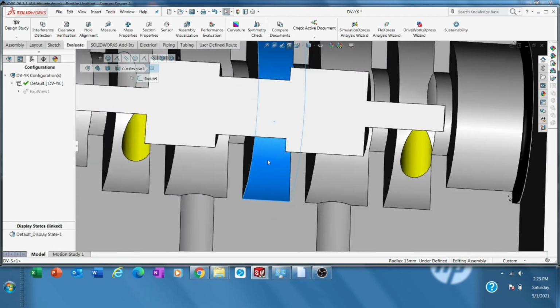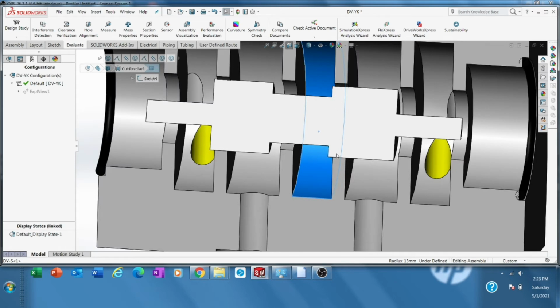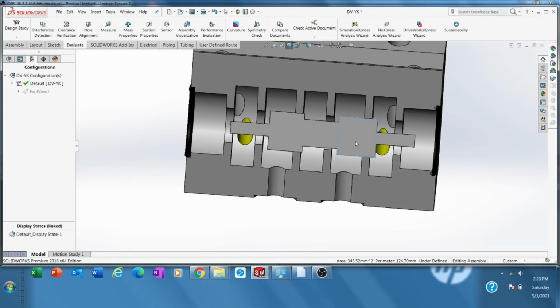The only chance this room gets mixing is from here, returning from B port. So that's the situation. If you want to go to center, it's idle position. You go to the right, the hydraulic piston will go down, and then you go to the center, it stops, and go to the left, the hydraulic piston will press up. As simple as that.